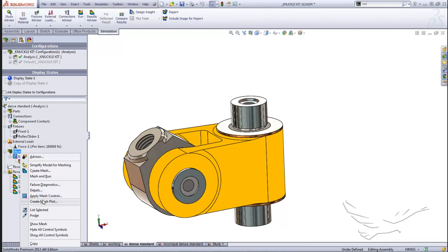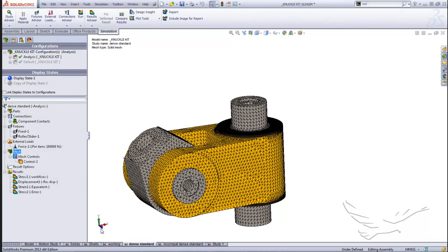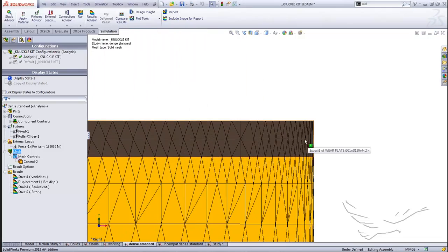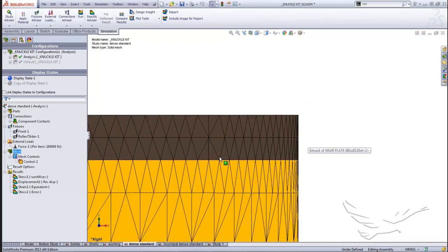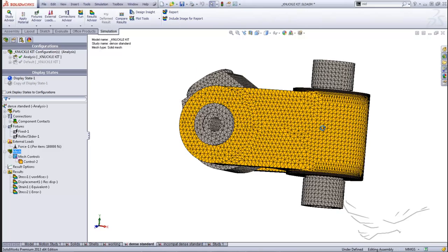For example, when we look at this standard mesh, the idea is that we want to make sure we capture bending properly. And in order to capture the bending and various other phenomena properly, we need at least 2 elements across the thickness of our washer. And so that's what I've done here. And that's how we end up with so many elements, like about 1 million degrees of freedom just for a couple of those washers.